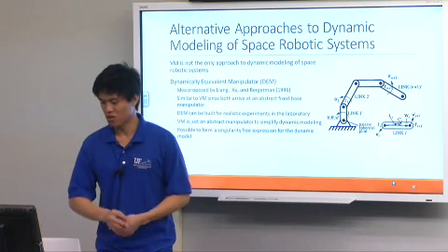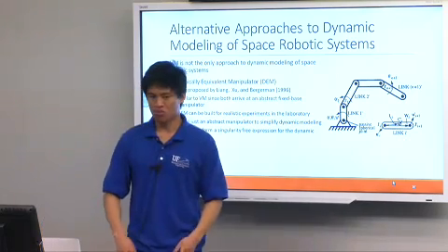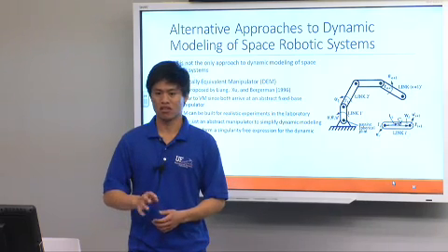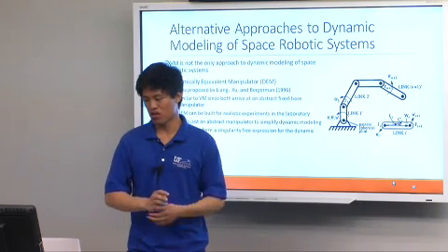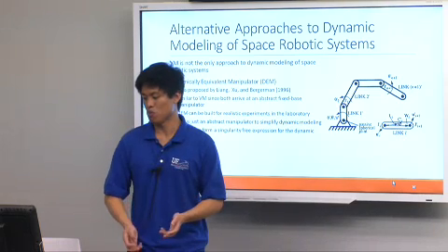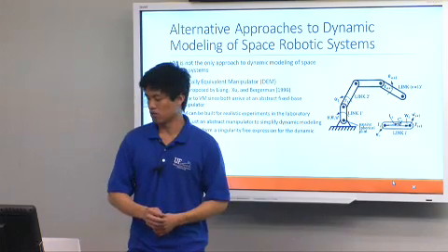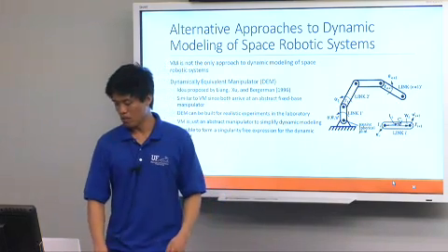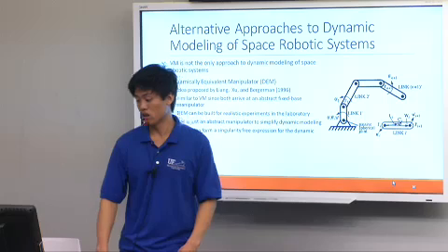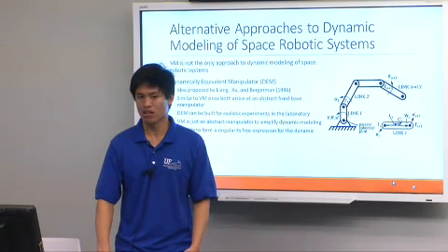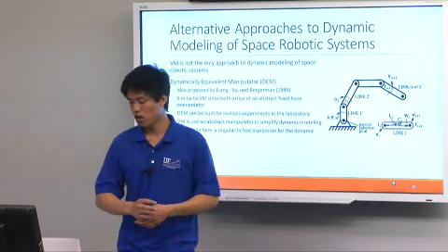So I was going to go over this. The virtual manipulator is only one approach to modeling robotic systems. There's another one called the dynamically equivalent manipulator, proposed by Ling, Xu, and Bergerman, I think from Carnegie Mellon. It's similar to the virtual manipulator in that they both arrive at some abstract fixed-base manipulator that maps its motion to the real manipulator.